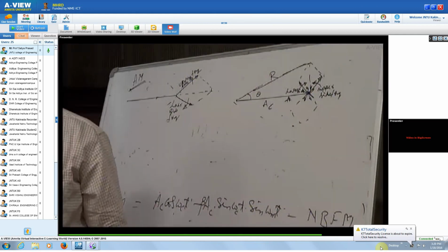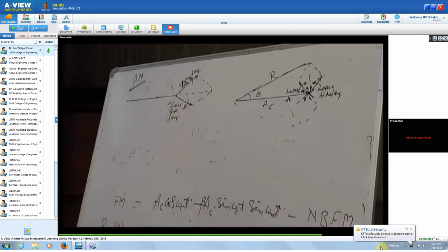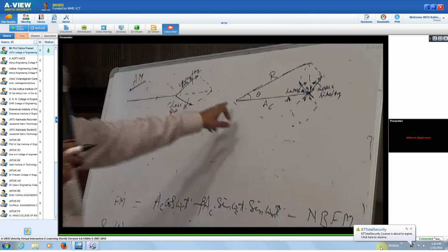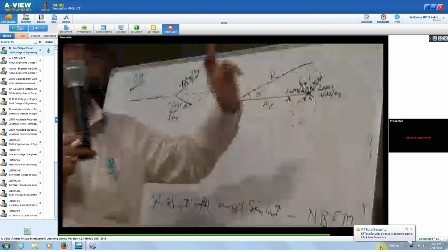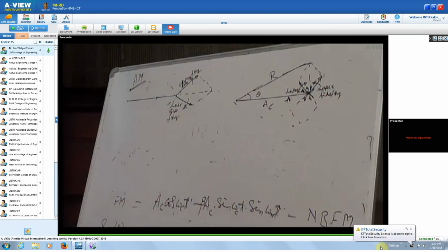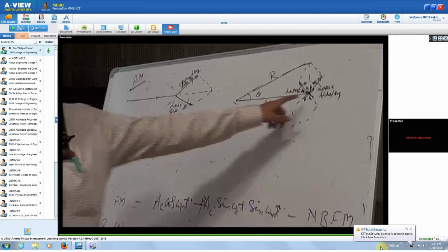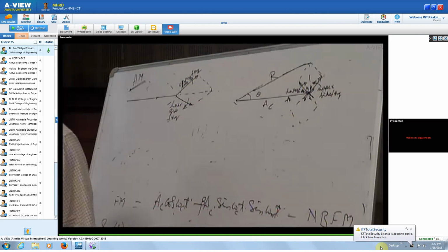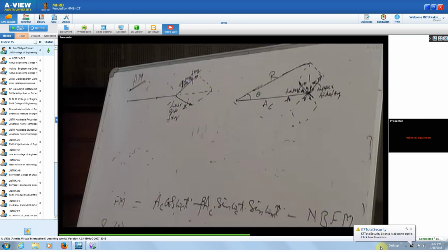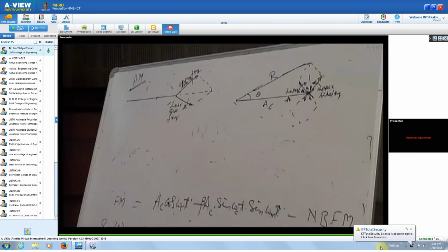But when you have these beta plus 1 phasors, you are going to add together to give you a wideband FM. Then you are going to get all those phasors combined together, plus minus and so on, depending on the values of Fc and Fm. So combined, we are going to get a constant amplitude wideband FM signal when beta is large. Right? So that is your phasor diagram for AM and phasor diagram of the FM signal, the narrowband FM.